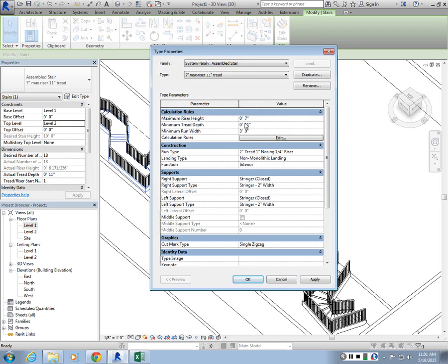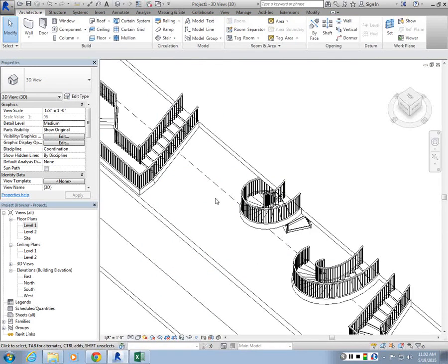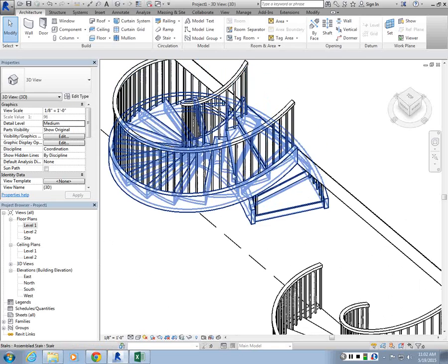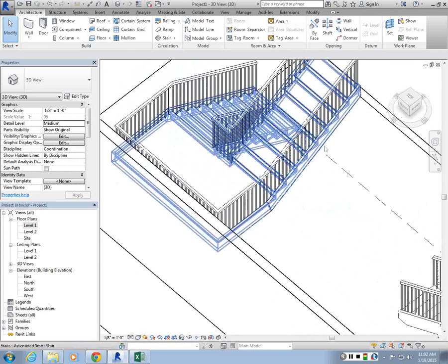And you can also choose different dimensions for the heights and the treads. But be careful, because when you mess around with these, the number of steps and the calculations starts to get messy. So what I realize is it's normally the best when you have Revit automating that process for you, so that you just stretch the floor heights and then you get more steps added to your stairs, basically. I'm going to show you how you can customize these objects as well. So you can choose the stairs, and let's say you want to change, let's look up this one for instance. Let's say you want to change the side panel here.